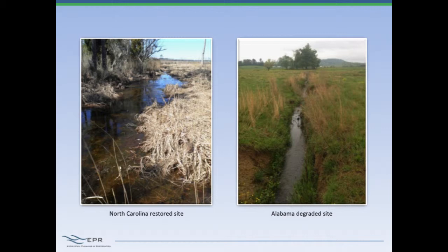Valley slope is sort of a surrogate for energy. So the steeper the valley slope, the faster that water is going to be flowing, therefore more energy to do work and actually cut channels, scour, and do those types of processes. As we stratified them out on this scale by channel form, we saw these nice breaks that developed. So as you get down in this region where you've got low slope and relatively low watershed areas, you really don't get a lot of channel formation.